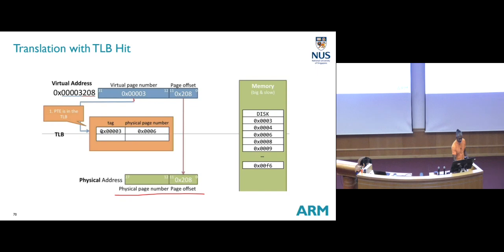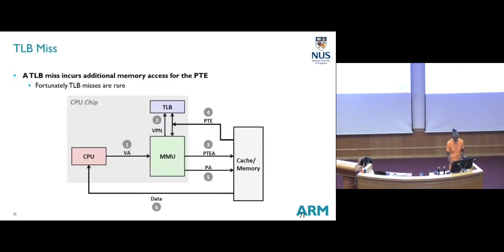The virtual page number will point to an entry in the on-chip TLB, and from the on-chip TLB I take the physical page number, copy it over here, I get the entire address, and then I access the memory. So the behavior is still the same, but it's now far more efficient. Why? Because I don't need to step outside of the processor. Within the processor space itself, I'm able to get this information that I want.